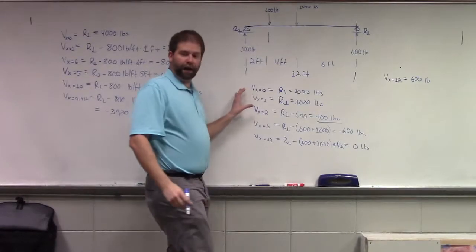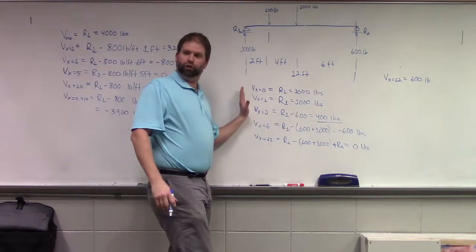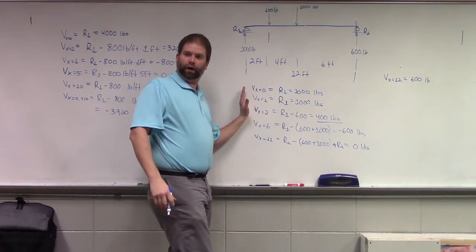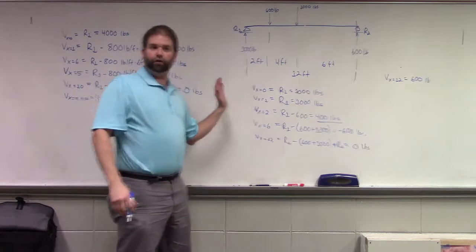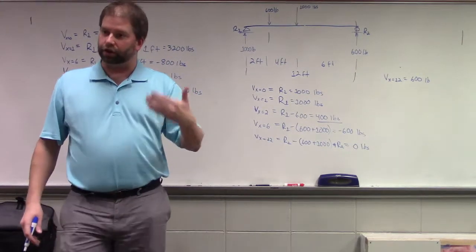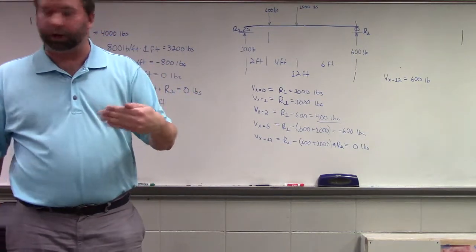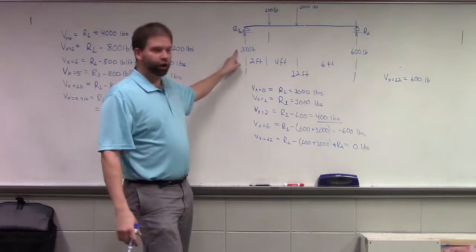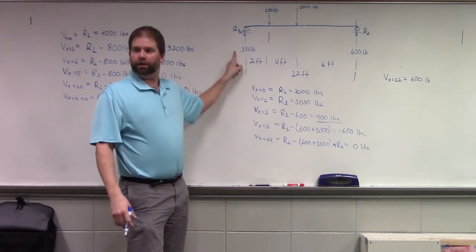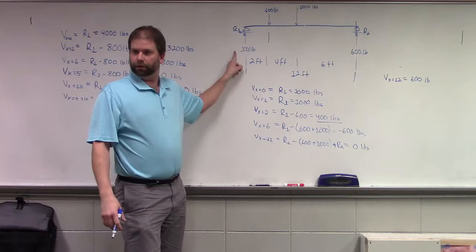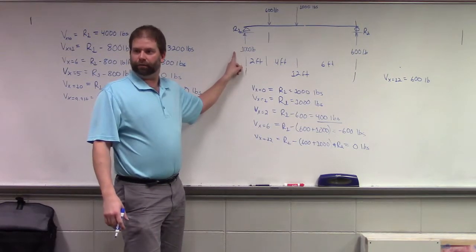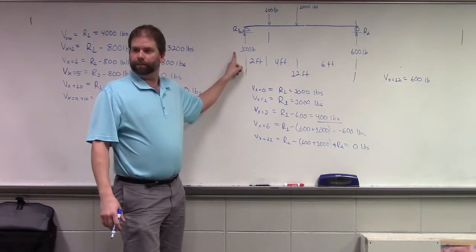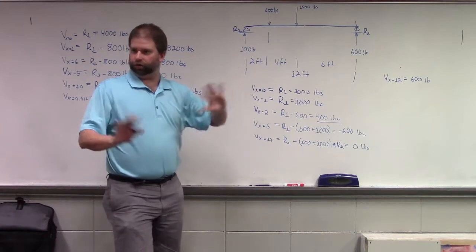You read my mind. I would ask you to do shear calculations going in one direction, and knowing what you know, that the maximum shear occurs at the larger reaction, I would begin your analysis from there, okay? Because that's going to give you your maximum shear, and that's what we're looking for. Yep, it's all we care about with shear.